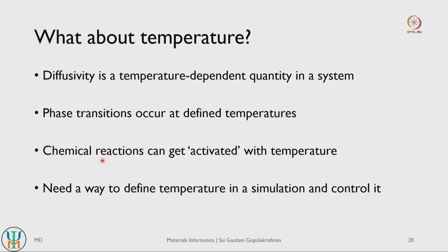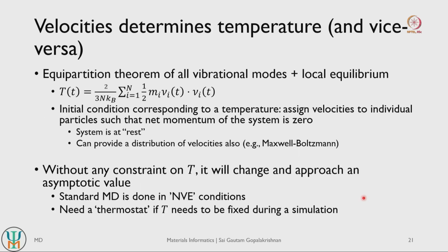So if you are interested in simulating any of these, you need to put into place temperature within your simulations. So we need to find a way to define temperature in the simulation and also find a way to control it, right, because we are solving Newton's laws. So we need to find a way to define temperature. And the way we actually determine temperature is using particle velocities, right.